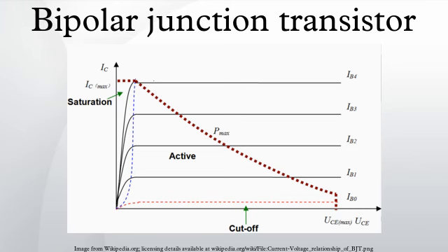Avalanche breakdown region. Although these regions are well defined for sufficiently large applied voltage, they overlap somewhat for small biases. For example, in the typical grounded emitter configuration of an NPN BJT used as a pull-down switch in digital logic, the off-state never involves a reverse bias junction because the base voltage never goes below ground. Nevertheless, the forward bias is close enough to zero that essentially no current flows, so this end of the forward active region can be regarded as the cutoff region.